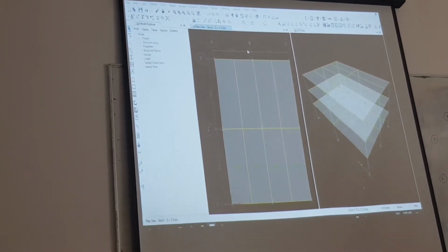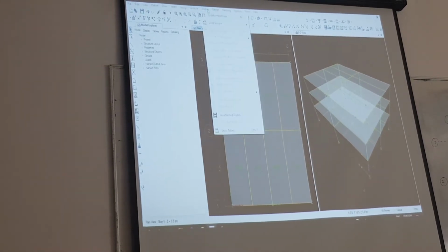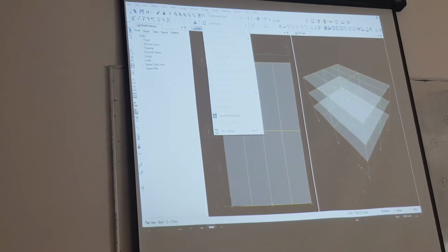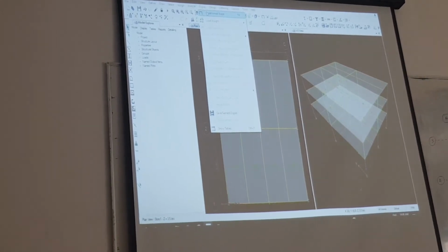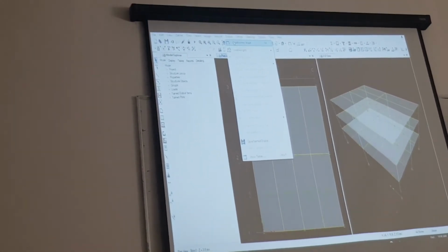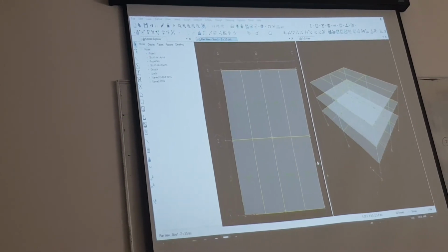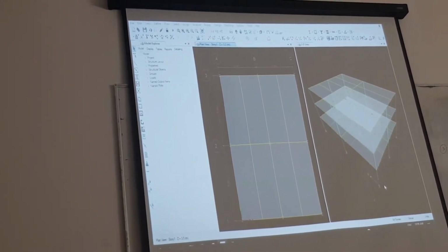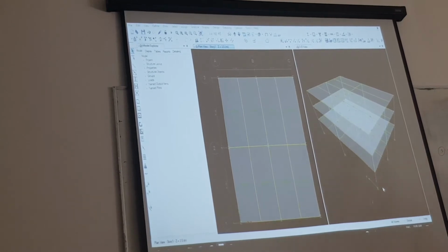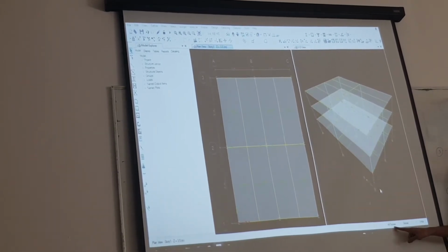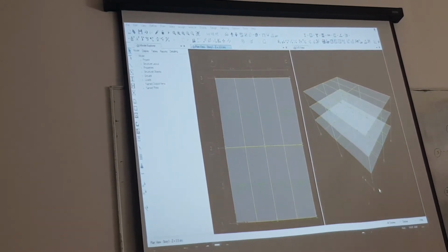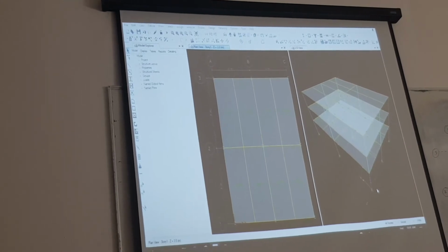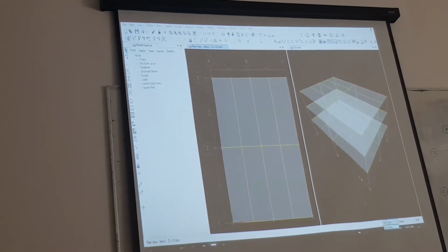So, if you go to this story 1, I will first suggest you go to display and click on undeformed shape. Okay, now after clicking undeformed shape, since you are going to define the diaphragms for the individual stories, you have to change all stories to single story, right? So select that option. Select one story.